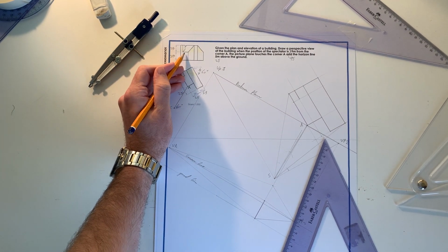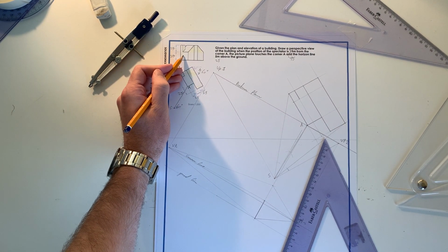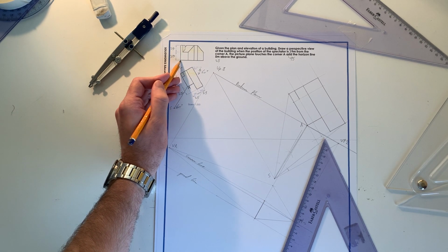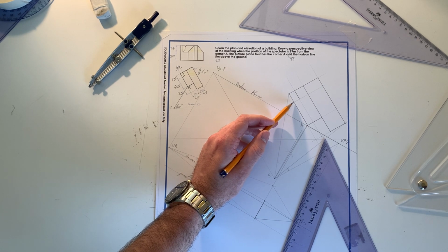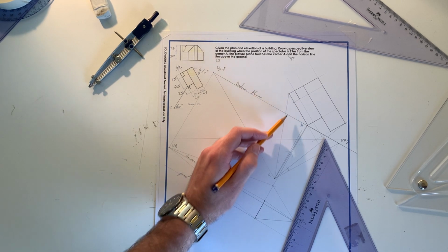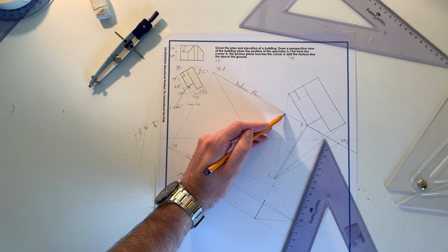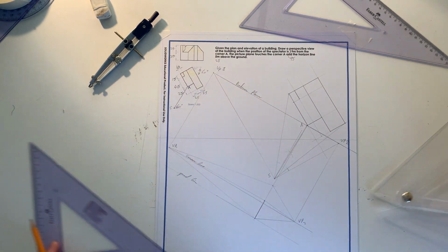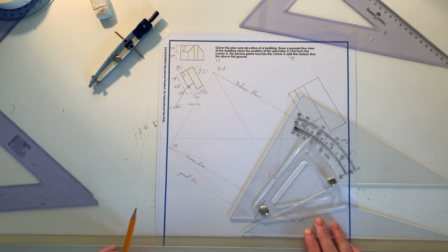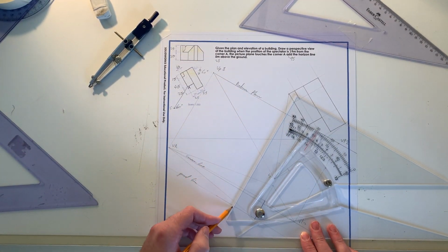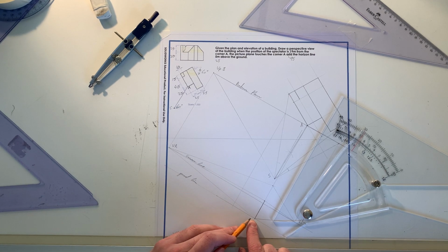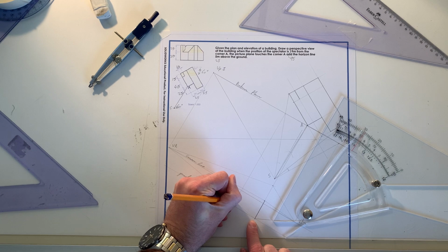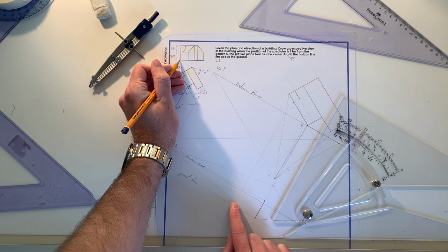So this kind of an L surface here, from the chimney down and this side panel. To do that, I also need this corner. So if I locate this corner back here, the plan that I've drawn is here. Join that back to my spectator. Where that line intersects my picture plane, I can carry that down. And where that intersects my line here, which travels all the way back to my vanishing point 1, is that corner. So that corner there is now this corner below here.